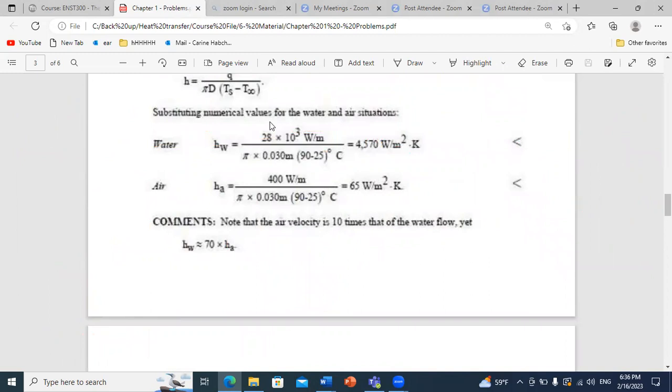So here, if you compare, look, it's very good to know the order of the convective coefficient of water. You don't have to remember orders, but it's good for you to do verification and just know approximately the order. In the course material, we have given the approximate order of the convective coefficient for different phases, if you have a liquid, if you have gas, etc. You can see here that it's of the order of thousands, while for air it's less than 100.